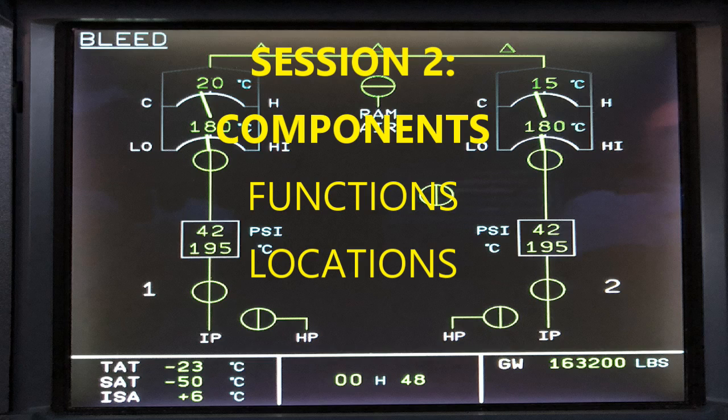That one is actually located in the engine pylon, because remember I mentioned the precooler, heat exchanger, all that, and the fan air valve is located in the engine pylon. Well, guess what? The bleed override solenoid is also located in the engine pylon, in the area after the heat exchanger. It's on a bracket in there, connecting to the HPV PRV coupling sense line, because it has to do with the high pressure bleed valve. So that's where that is in relation to the other components.